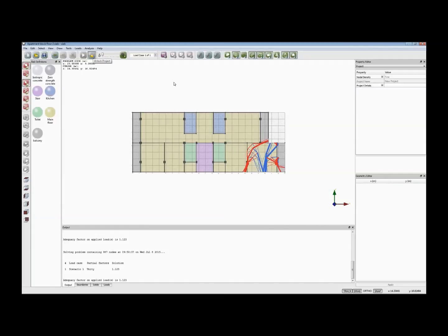So that's given you a very quick flavour of how you can put in a geometry and material properties, etc. for an existing building slab and see what happens when you maybe change the usage of it, and you can use it to easily determine whether or not you can take this extra load or not. So that brings us on, if I bring up the PowerPoint,